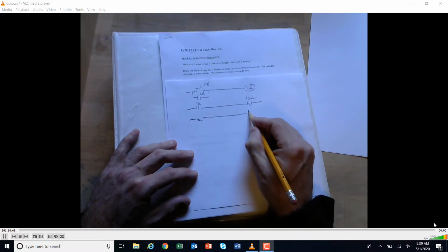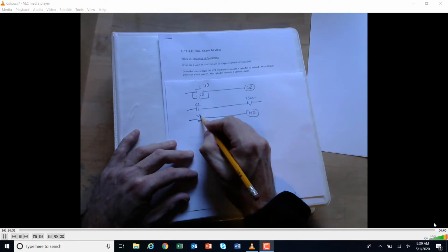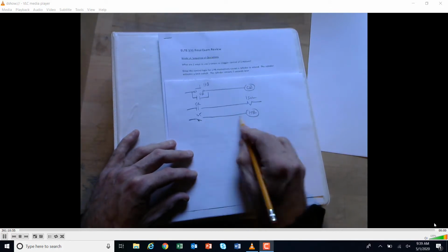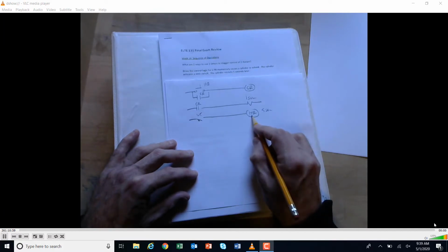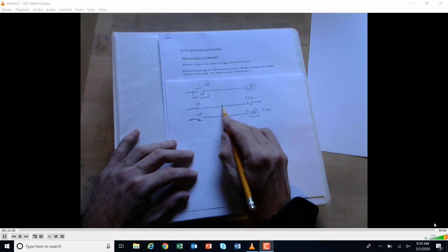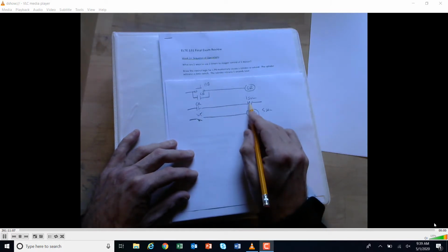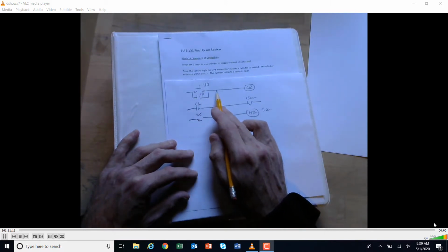is going to start a timed relay. Okay, this is the 1LS. This means that the cylinder has extended. This is going to count 5 seconds. And then what do we want to do? We want to retract the cylinder. Well, let's not put it here. This would be a place to put the contact to cause that to go off. But let's just stop the whole process because we have memory here.